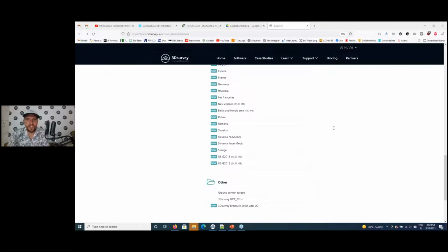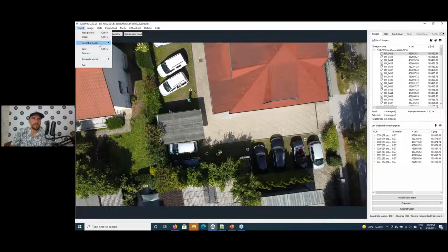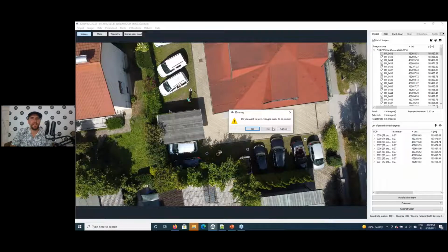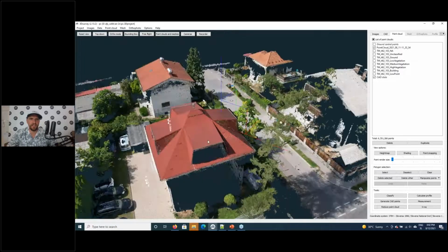And the final question today: the difference between the LiDAR and drone survey is systematic. I mean, if you fly at 30 meters, it will always be 6 to 7 centimeters above. So in this example that we had here, the difference was systematic, yes. When we saw that this area is systematic, we said, perfect. That probably just means we used the GPS to measure this point, and the LiDAR used its own GPS. We expect there to be some systematic difference between the two, maybe a few centimeters, something like that.